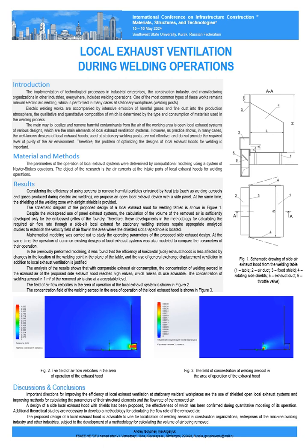The field of air flow velocities in the area of operation of the local exhaust system is shown in Figure 2. The concentration field of the welding aerosol in the area of operation of the local exhaust hood is shown in Figure 3. The analysis of the results shows that with comparable exhaust air consumption, the concentration of welding aerosol in the exhaust air of the proposed side exhaust hood reaches high values, which makes its use advisable.